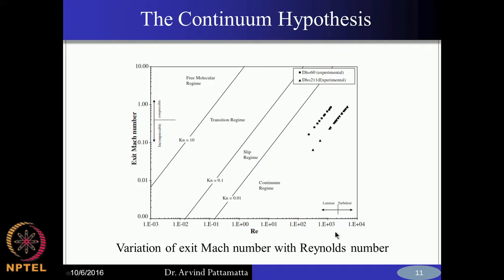What is interesting here is that you are in the laminar regime, where we are talking about Reynolds numbers less than 1000. Most of these microchannels, since you have very small diameters, will not cross the laminar regime, in 99% of the cases. Even when you are talking about very high velocities, as you can see here, the Mach number could sometimes cross 0.31 and so on, but the corresponding Reynolds number will always be less than 1000. These are very small diameter tubes. So, in terms of Reynolds number, you are doing good. You do not have the problem of analyzing a turbulent flow.